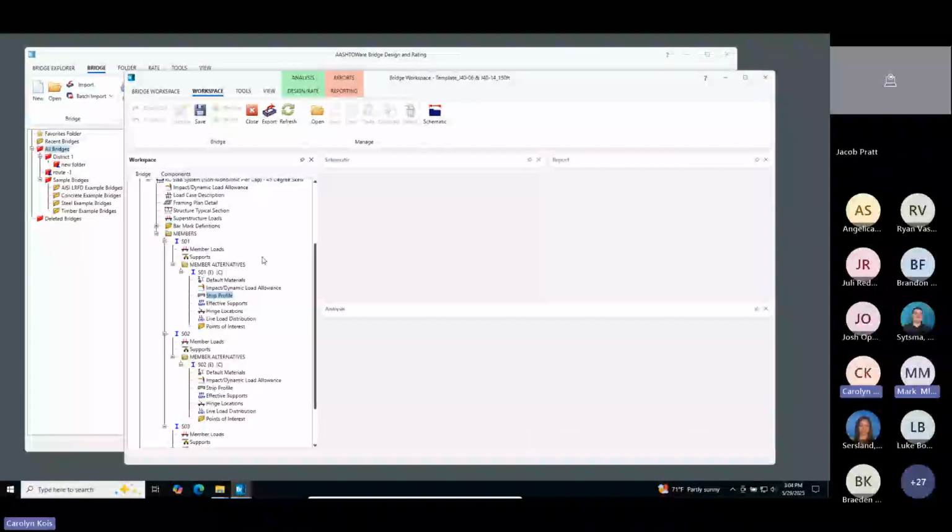Good point. And just to reiterate, it is a line model analysis for slabs. So when we have those different strips set up, it looks at the width and the reinforcement and the capacity that's generated by that width. It'll look at the portion of the dead load and live load that goes to that width, and then analyze that on a line model type of basis. So it's not like a 3D slab analysis per se. Just one other thing to note.